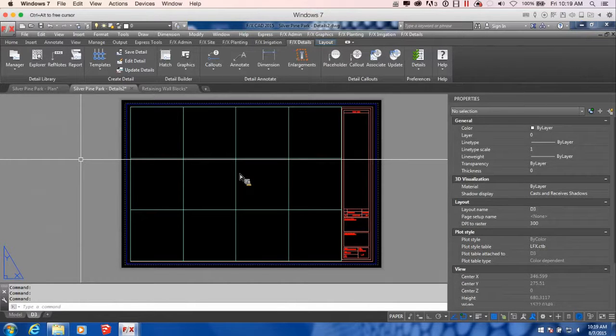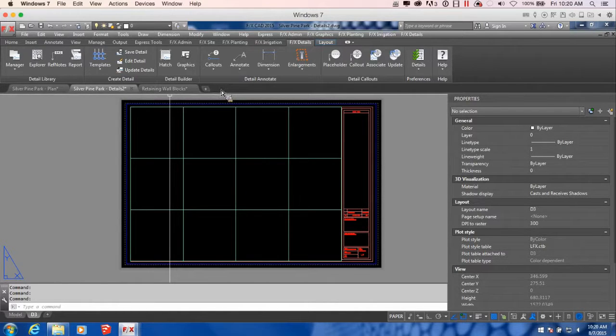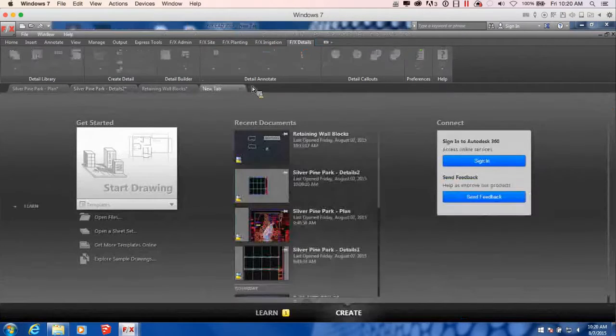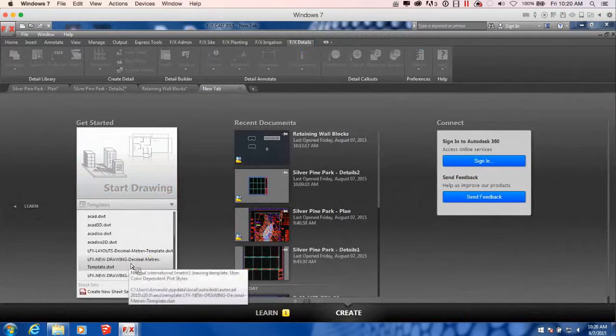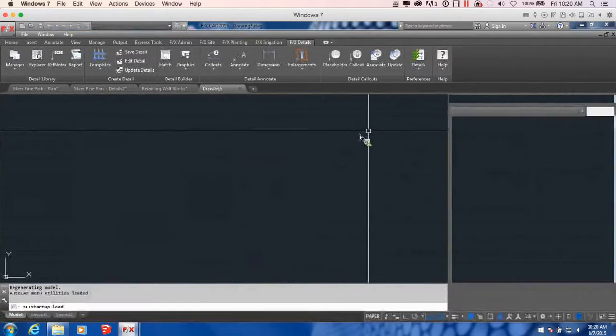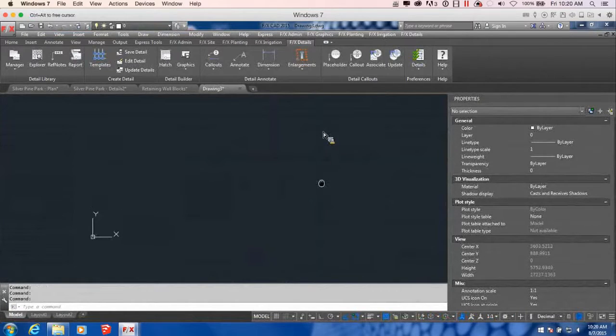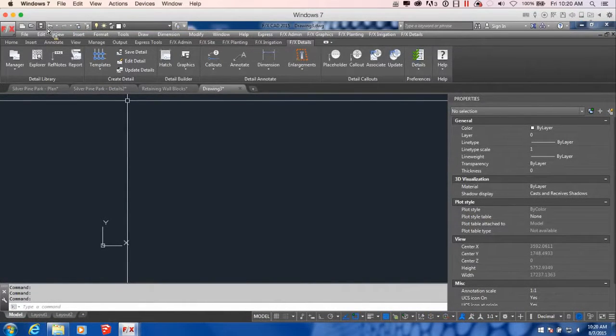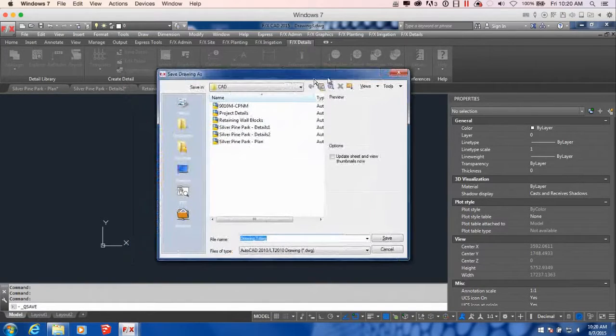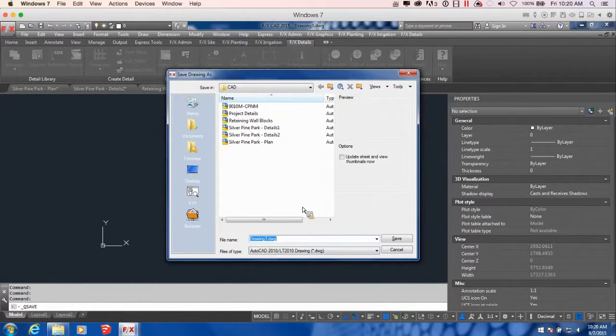And especially for the process that we're going to do, I'll go into it, but we're going to use the batch save option. So I'm going to want to save my drawing to be able to access it later and re-batch save as necessary if I need to make any adjustments through the process. So I'm going to open up a brand new drawing in millimeters, or inches if you're in Imperial. And I'm going to save that right away because I'm going to do the batch save process and I'm going to put 2 details into this file. And I'm just going to call it project details.